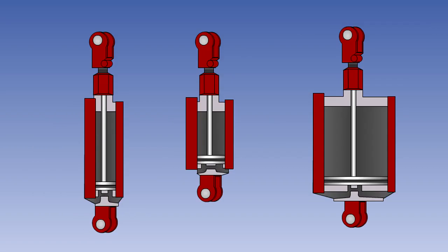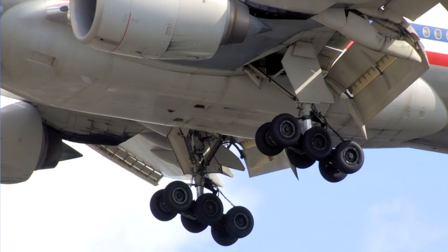The power required for operating different services varies according to their size and loading. This can be catered for by using actuators with pistons of different areas for different work as required by the load, whilst keeping the pump output pressure constant. For instance, main undercarriage up jacks will need pistons with a very large surface area, whilst individual spoiler panels will have relatively small pistons.